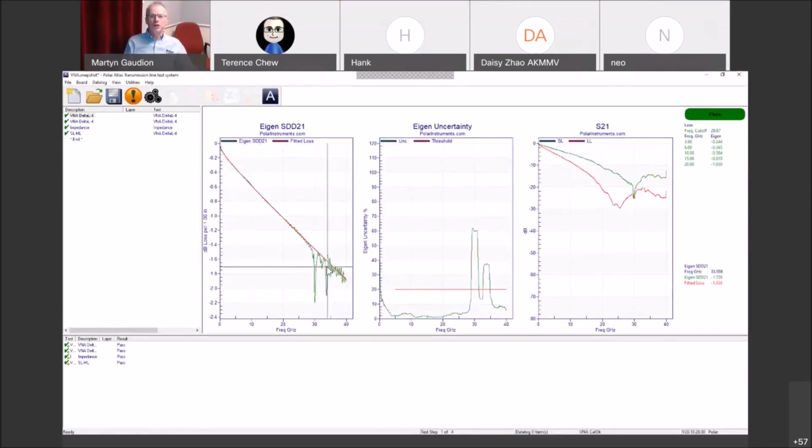So what you can see here is as the frequency goes up, you'll sometimes get effects which are dips down here, or you'll get variations in the measurement as the frequency goes up and above and below the actual line for the insertion loss. Delta-L looks at the points either side of the point that's being analyzed to see if they're in the same sort of area, and uses that to enter the data into the line fit. So if there's a dip that goes wholly negative here, or a dip that just went totally positive, so if you've got a dip here from a via stub,